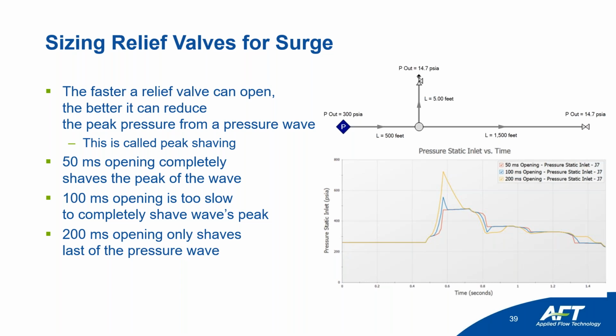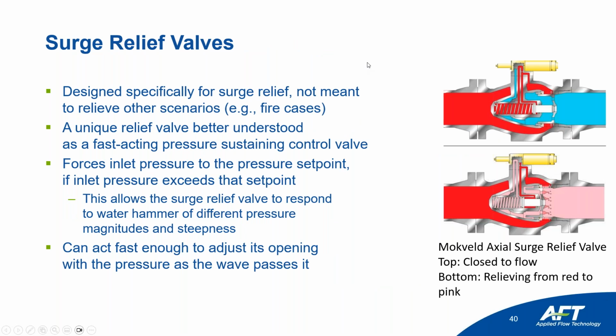So now it begs the question of, well, what if you didn't take a conventional relief valve? What if you designed one explicitly for surge? And that was why we worked with Jans at Mockfeld, and that was his primary contribution to this, something that is known as a surge relief valve. Surge relief valves are specifically designed for surge relief. They are not designed for other conventional scenarios. Because that is the use case you're designing for, it is often better understood as a pressure sustaining control valve because you place it at the location of the surge.